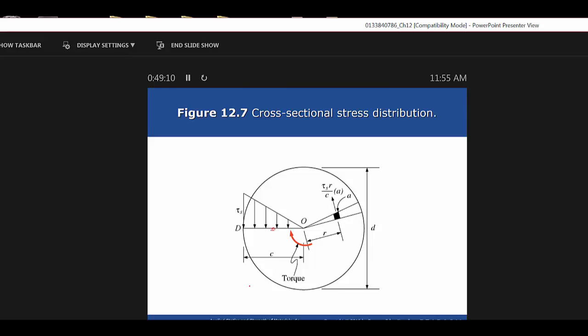I mean, you can break a shaft anywhere. It doesn't necessarily have to be at the thread. In the case of your bolt, it's more than likely going to break there. But I've sheared bolts off that I haven't actually sheared at the thread. Yeah, you can do that. Now, there's something else that made that happen. It might have been rusty, or it might have had a nick in it, something like that. But I just don't understand how, right at the center, there's nothing there. It's just theoretically void of...